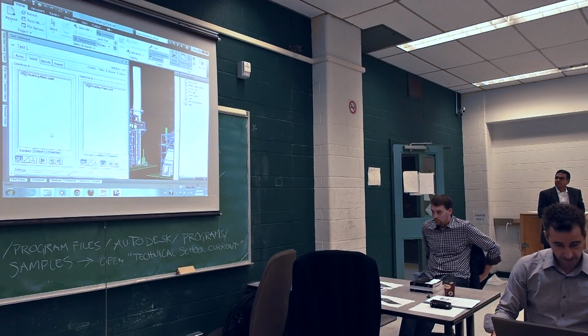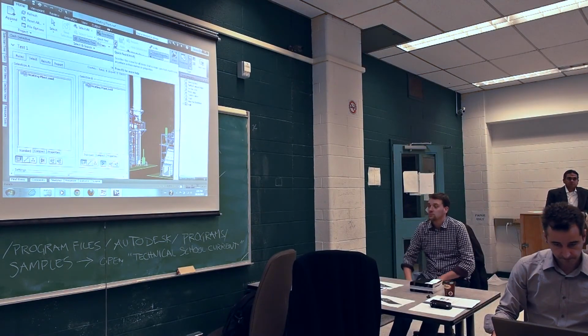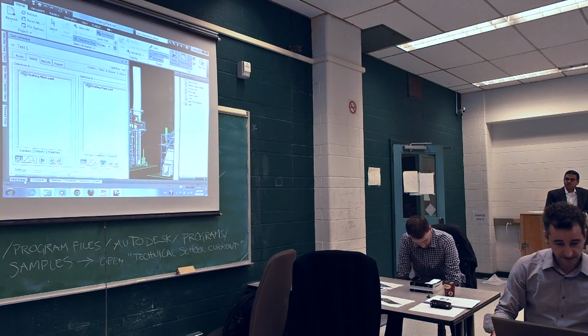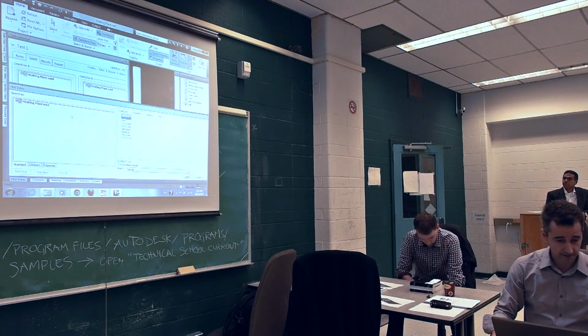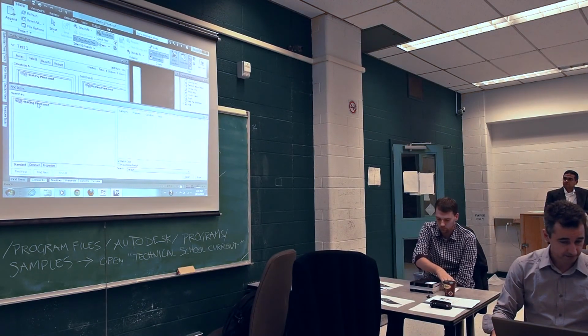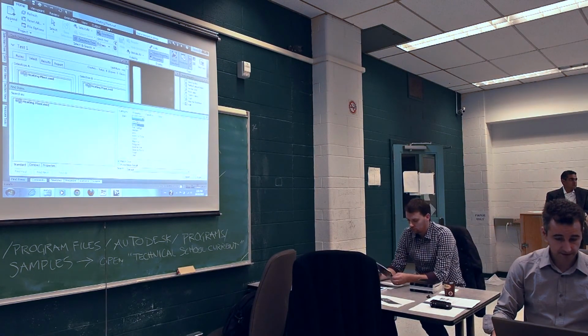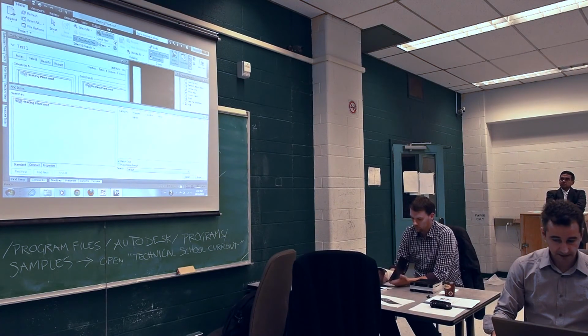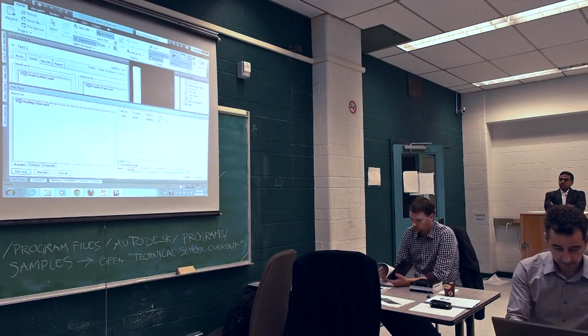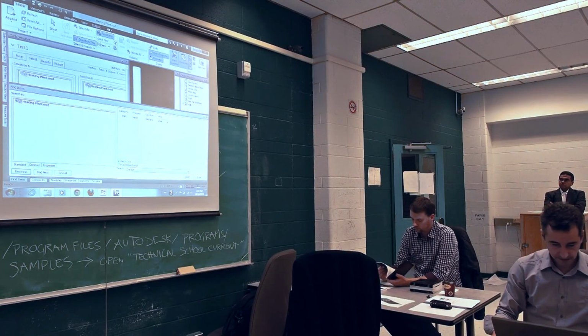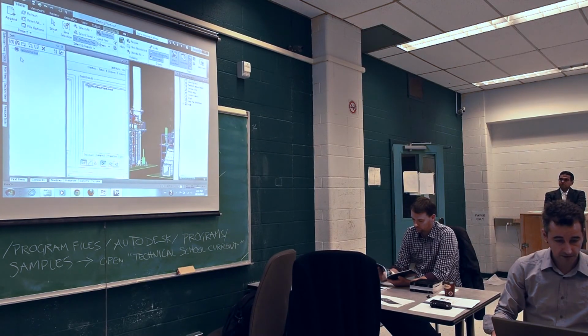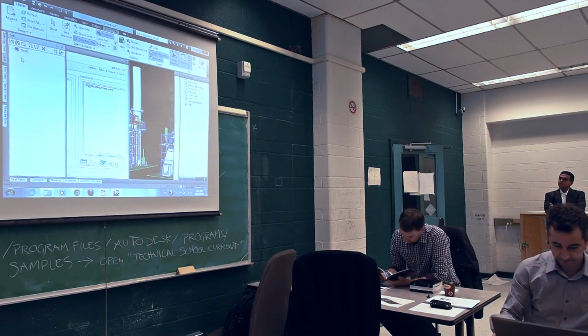So, in the find items, in this file, I'll find all the items with the name containing, let's say, steel. Match case not important, find all. And then I manage my selection sets and I'll create one which is called steel.